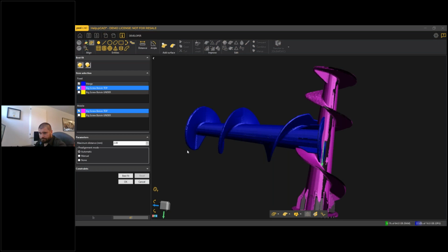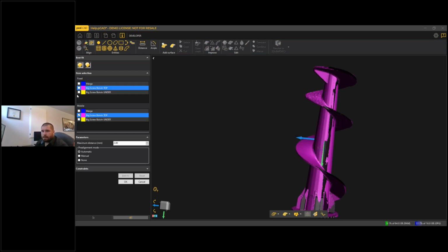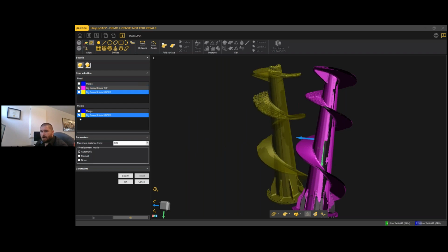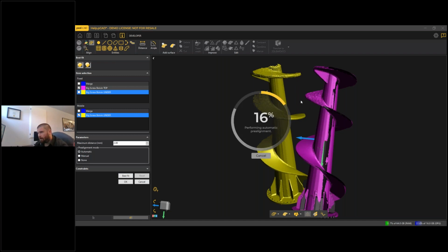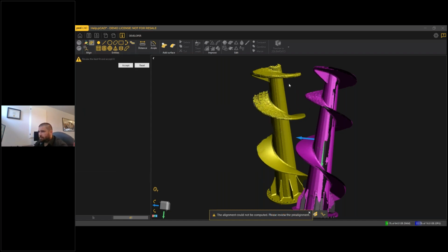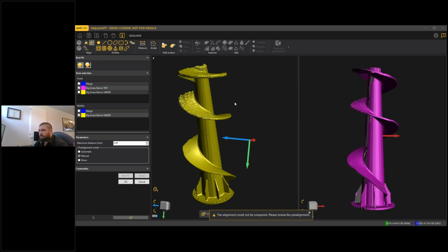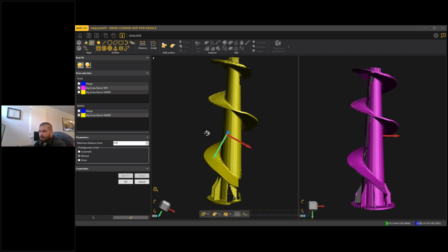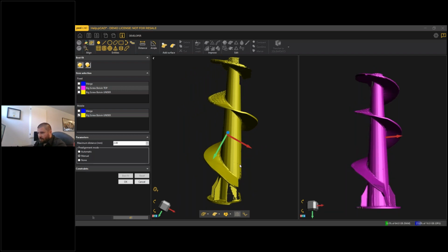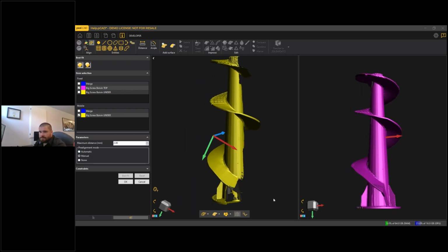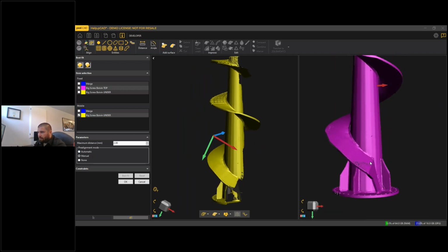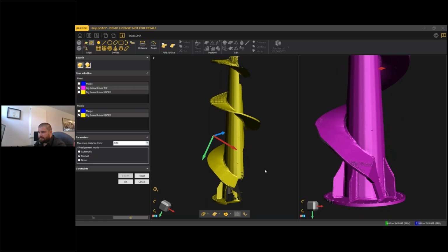From here, first thing I could do is try to do an automatic best fit. So the software will automatically try to put them together. This rarely works in a symmetrical part. So this is symmetrical, I mean, on the rotation. So we'll just give a little help to the software by using point pairs. So we'll use a 3-point, so it starts the best fit correctly.